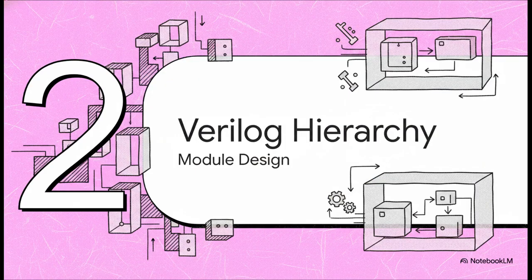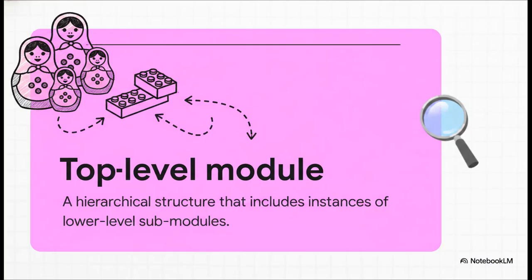So now that we understand the math, how do we actually organize all the code? Let's move right into Section 2, Mastering Verilog Module Hierarchy, to see how this scales up. Think of Verilog module hierarchy kinda like a set of nesting Russian dolls, or maybe a really organized box of Legos. As your hardware designs inevitably get larger and more complex, you can't just have all your logic floating around in one giant messy file. A top-level module acts as a hierarchical boundary, a neat organizational box that includes instances of smaller, highly dedicated lower-level hardware modules tucked away inside of it.